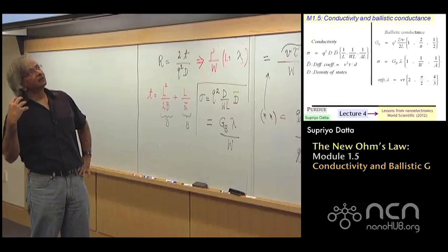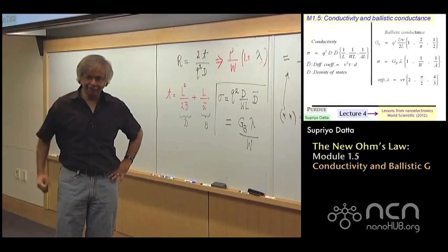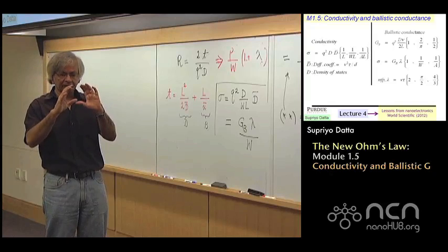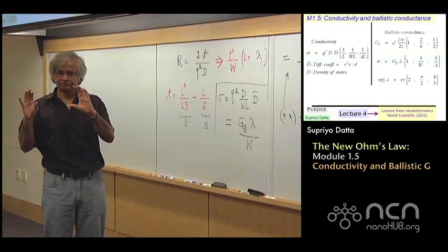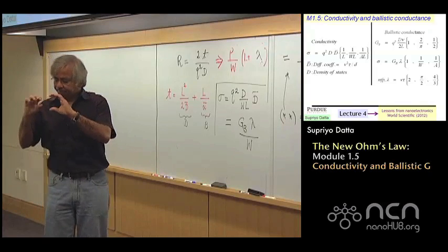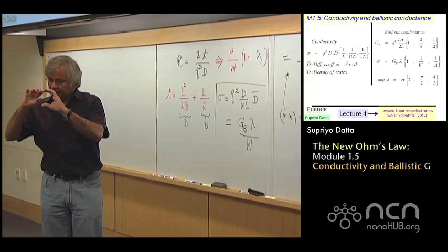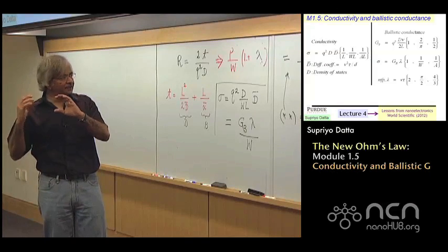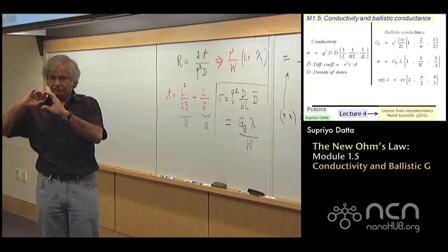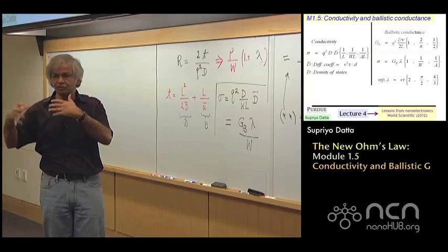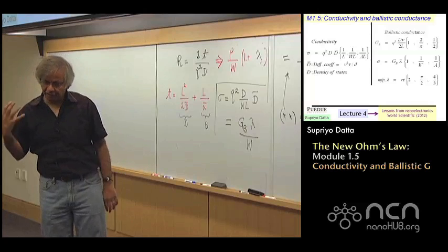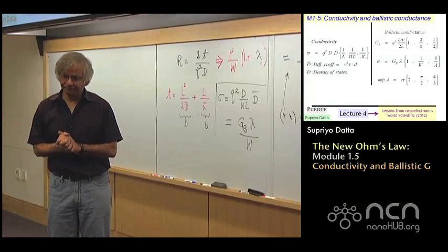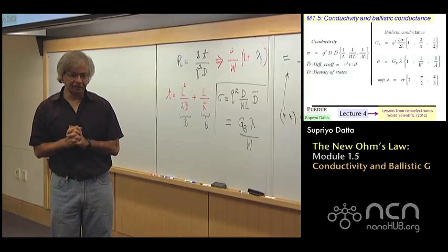Because the modern view of the way to think about conductivity would be something like, if I have a conductor and it's ballistic, then it has a certain conductance, which simply depends on the density of states and the velocity. That product is what you call the number of modes. It's what really represents the lanes on your highway. And that gives you the ballistic conductance.